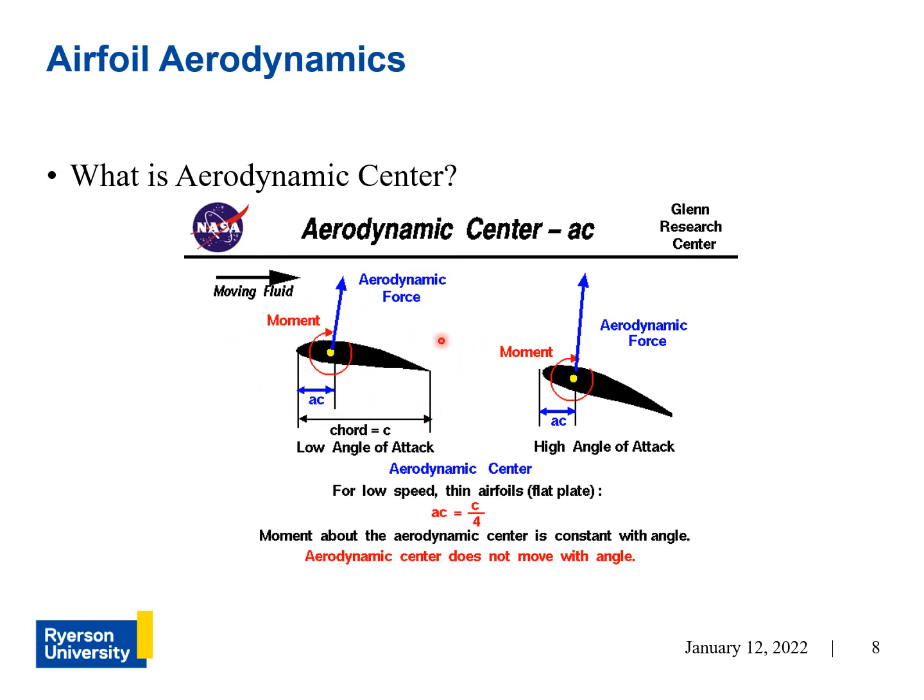But if you were to take the moment about a particular point on an airfoil and calculate it, and then change the angle of attack, and then take that moment again from the same spot, and repeat the same process as you increase or decrease the angle of attack, you'll see that the moment doesn't really change a lot at that particular point. And that's why it's important to take note of that point, and we call it the aerodynamic center.